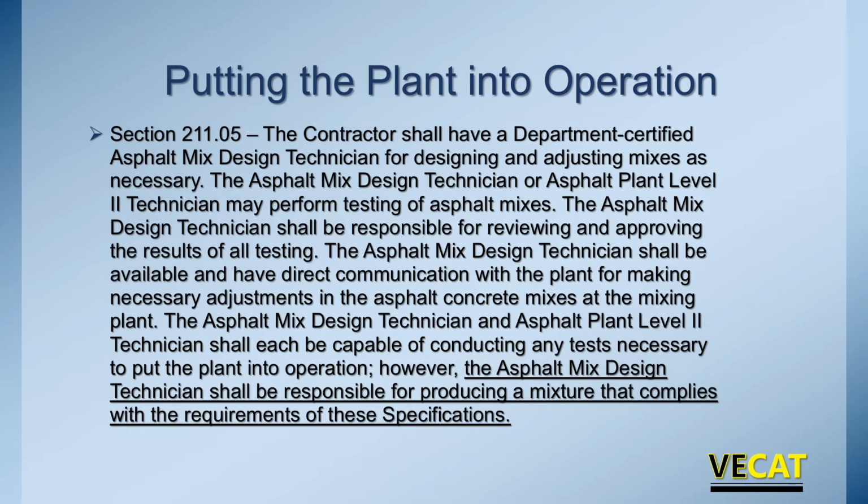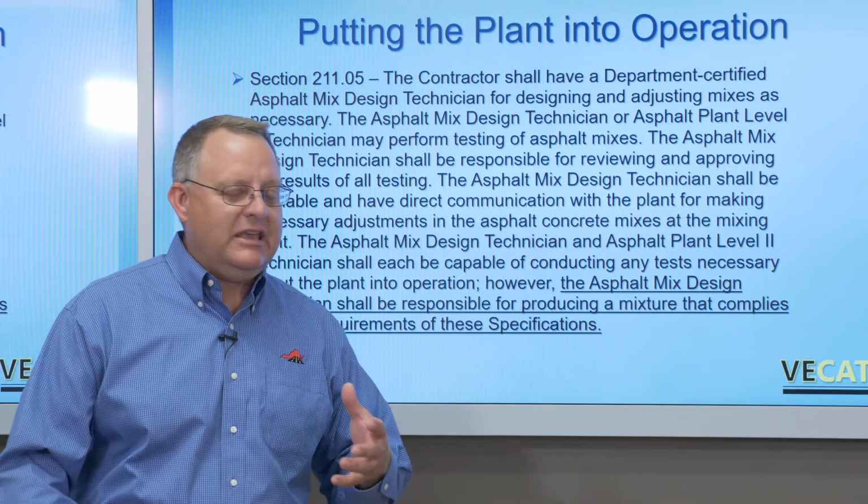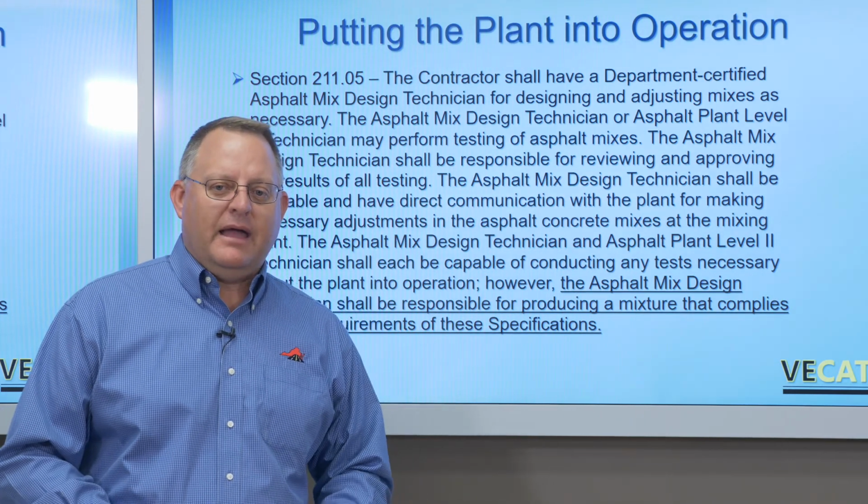Here is a long paragraph out of section 211.05. The one thing I do want to draw your attention to that separates that plant level 2 technician from the mix design technician is this very last sentence. The mix design technician shall be responsible for producing a mixture that complies with the requirements of these specifications. Level 2 does the testing. They can put a plant in operation. But the mix design technician is the one that makes sure that it's correct, that the mix is designed properly, as well as making any type of plant adjustments. So keep those things separated in your mind.